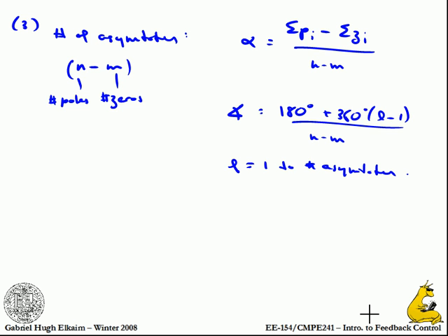But what this says is that however many poles you have in excess of zeros, these are the ones going off to infinity. All right. So if I have 3 poles, 1 zero, 2 of these are going off to infinity, because 1 pole is going to wind up at that zero. In this case, because I now know how to do the real axis, I can tell you that that pole is going there. I can tell you that these 2 are going to hit each other and they're going to split, and they're going to go up.